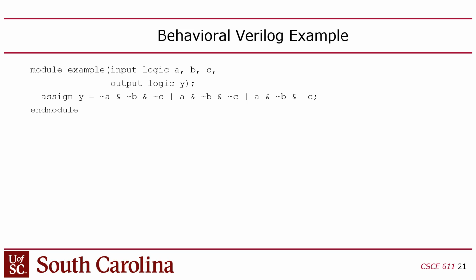When you compile with either of them, they convert your Verilog to C and then compile it as an executable. They take your design and the simulation engine and mash them together into one monolithic executable that you can run, which is cool, except there are two very horrible limitations.